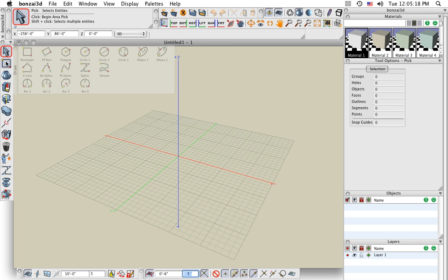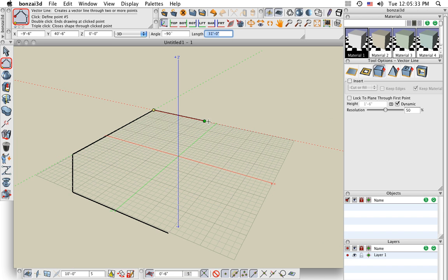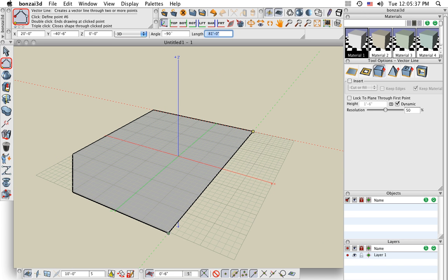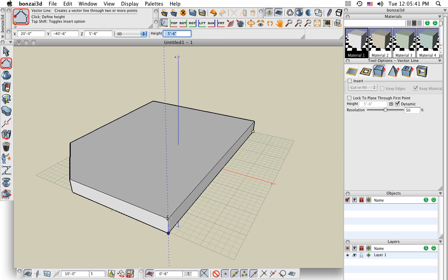Okay, so let me start a drawing with a basic shape here on the reference plane seen by the grid. I'll be snapping to 6-inch grid intervals. So just clicking, and you see these red and green lines. Those are called guidelines that help me line up my input shapes geometrically. I'm clicking back at the first point, closes the shape, and now I extrude this straight in 3D. One more click, and we're done.